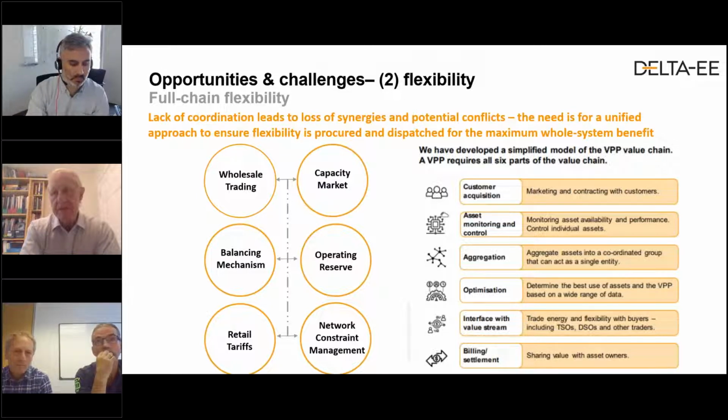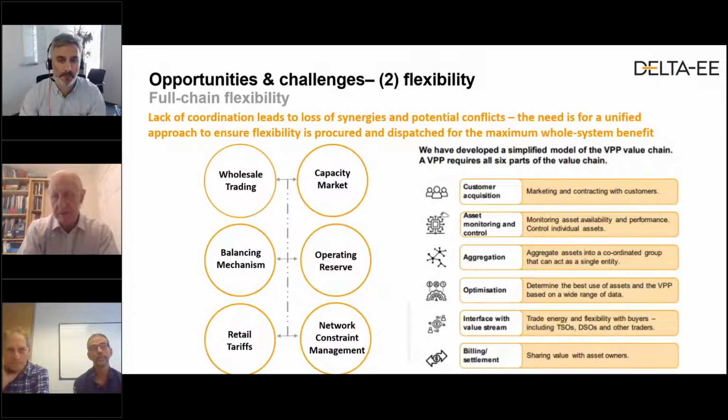Sure. So, in terms of functionality, for any country looking to decarbonise its power system and its energy demand, flexibility will become increasingly important. But the full value chain for flexibility has many components. So, for example, aggregators and virtual power plant operators for residual system balancing, transmission system operators for operating reserve, including demand downturn and upturn, capacity markets, which we've mentioned, e.g. batteries and demand side response, DSOs increasingly for distribution network constraint management to support networks under peak demand conditions and under planned outage conditions, and also to aid post-fault restoration in certain circumstances, and wholesale day ahead and intraday markets.